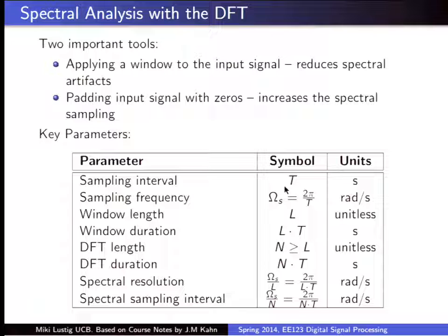Actually, the whole bandwidth, if you take negative and positive frequencies, it is 1 over T. It's just that the highest frequency is 1 over T over 2. Okay? But you have the positive half and then the negative half. And if you had a complex signal, right, then you would see a whole range of 1 over T hertz.